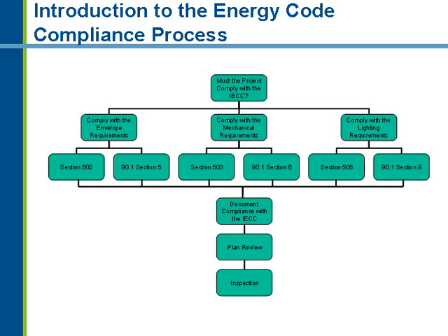In the 2006 code, the definition for conditioned space basically says that any space that has space conditioning equipment is considered conditioned space. The only cutoff on that is a building that is conditioned less than 3.4 BTUs per square foot, and that's considered a low energy use building. So essentially any building with a space conditioning system, either heating or cooling, is going to be considered conditioned space under the 2006 IECC.